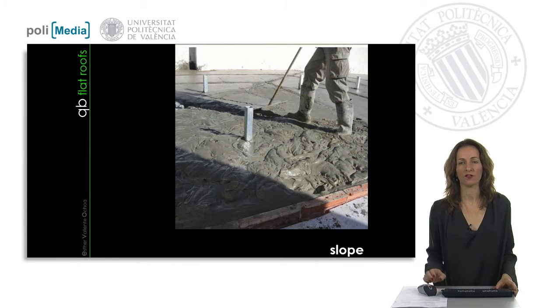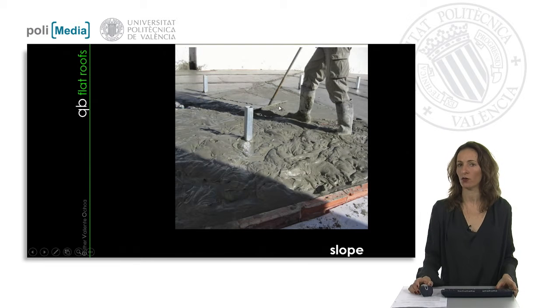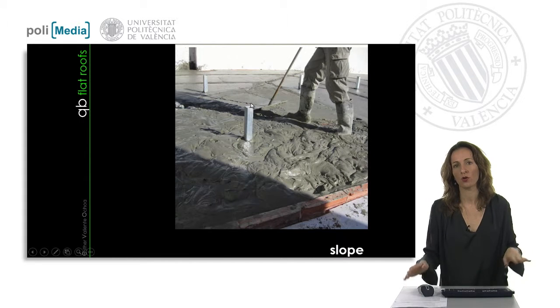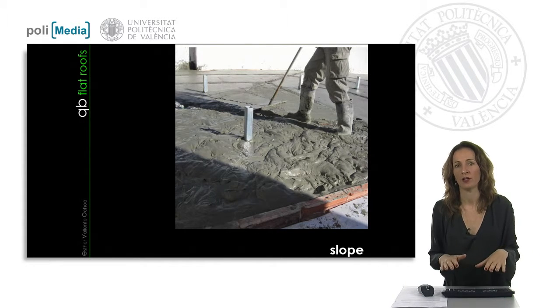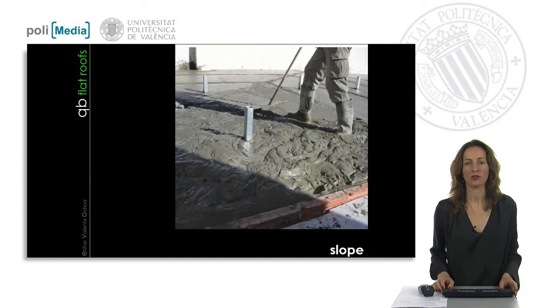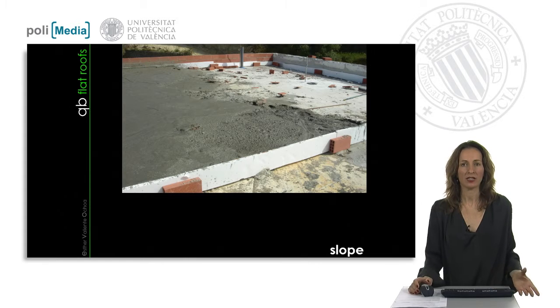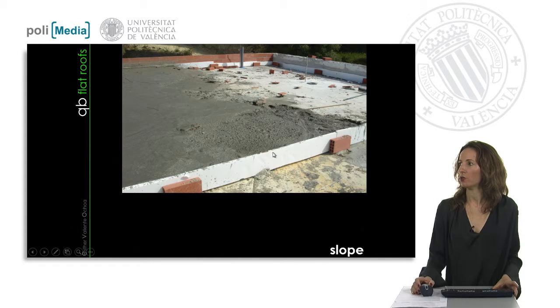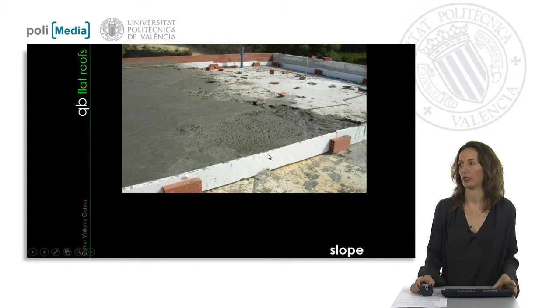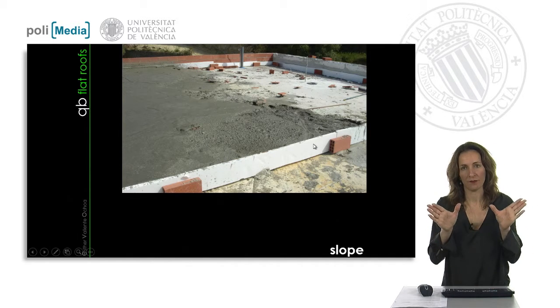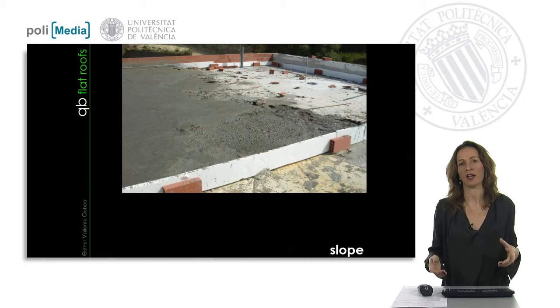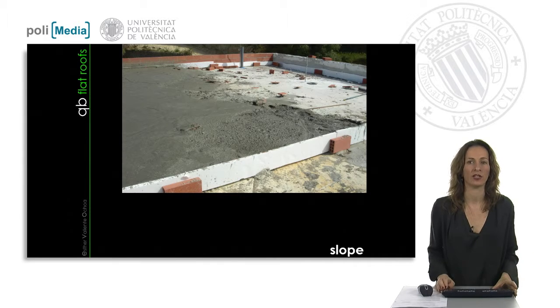During the slope we also have to check if the compacting is well done with an electrical or hand tool in order to keep the surface and also close all the possible small holes, because if not, it will not be easy to moisturize and keep the moisture in our mass. In the slope we can also use elastic materials that help the unit to have a little bit of dilatation, a little bit of movement. In this case we can see in the boundary areas a piece of polystyrene making the perimeter, the boundary of the unit, while allowing future movement of the unit.